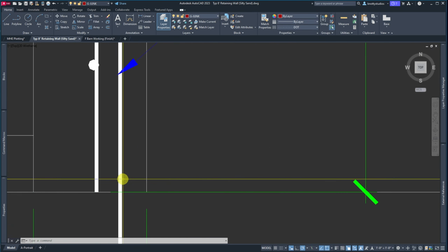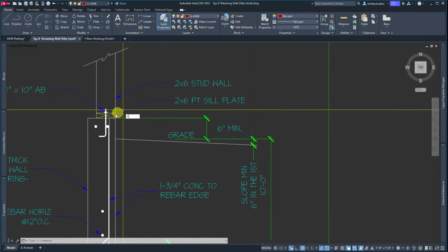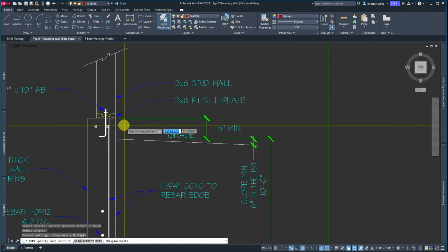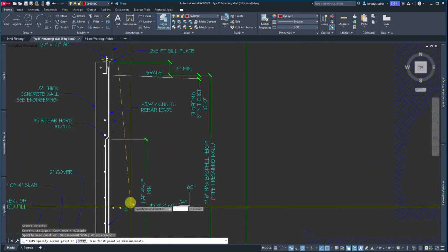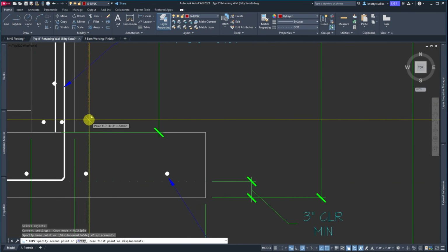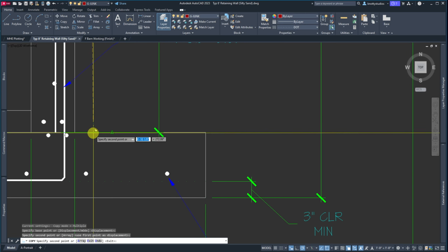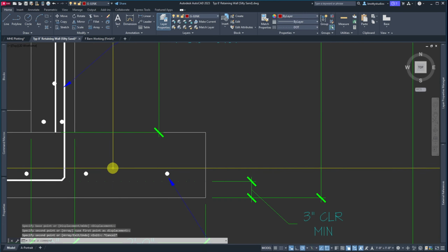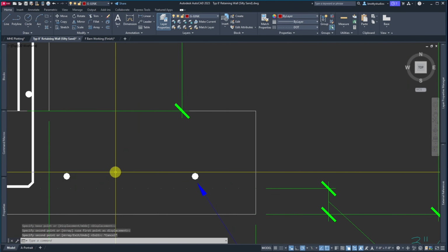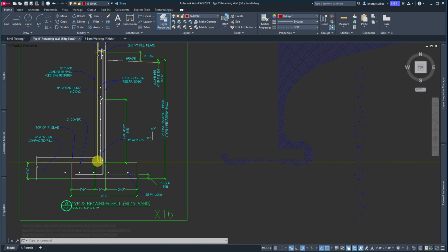So now I need a double down here at the bottom. So I'm just going to grab this because it's already spaced right. Let's just copy it, bring it down, and put it towards the bottom here. And if you get it about midway in your slab there, you're probably in really good shape. We got concrete above and below. So this is not a serious clearance issue, but you want it to be in a bond beam type of location.